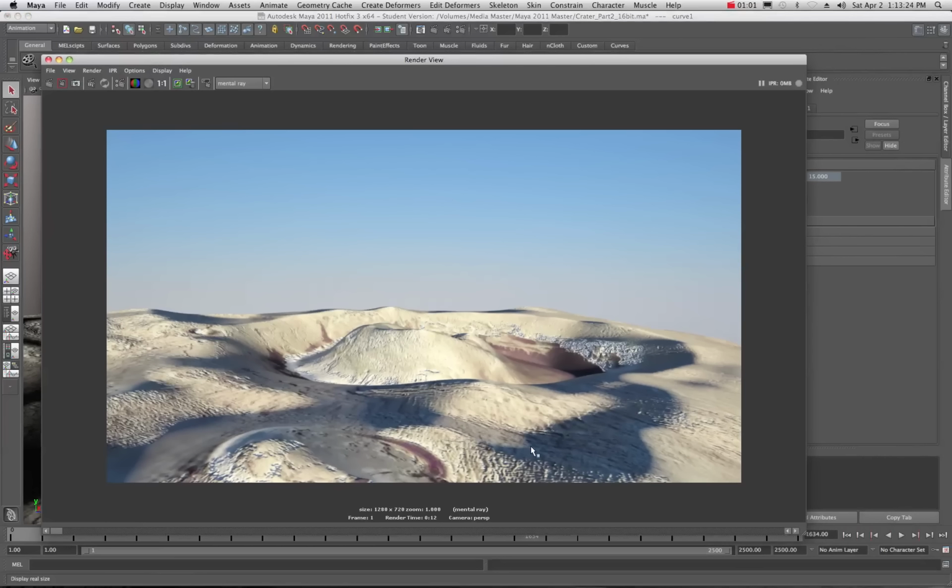And in the previous tutorial, we output an 8-bit mesh and noticed some aliasing and some artifacts and some weird stair-stepping and things like that. And sometimes all of that stair-stepping and stuff can be smoothed out using a 16-bit terrain map or mesh. So you've got to remember that a 16-bit is going to have a lot more information in it and a lot more faces and all of that. So essentially this is what we're looking at, and we've made some adjustments to the Photoshop file, the original image, and let's take a look at those for a moment.